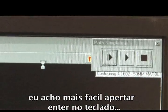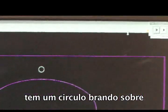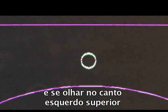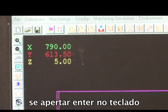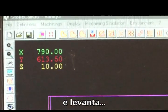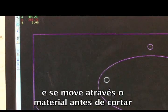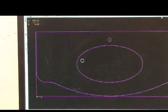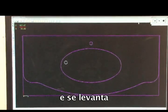I find it easier to press enter on the keyboard, and if you look where the tap hole is, you can see that there's a white circle there now above it, and if you look to the top left hand corner, it's 5mm above the material in Z. If I press enter on the keyboard, it drops to -23 and lifts up to 30mm above the material and moves across to the hole before routering. Drops down onto the circle to -23 and lifts out.